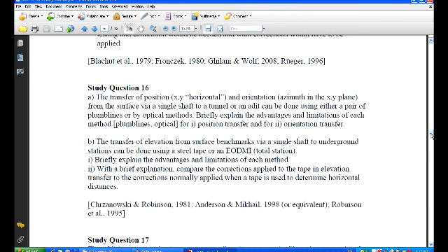However, there's also the problem that with an optical plummet you either have to be above or below where you're wanting to have the horizontal positioning done, which means if there's a sump at the bottom of the shaft, there would have to be a fairly sophisticated platform, and you can imagine how sophisticated it would have to be in order for the instrument not to be vibrating. And similarly, there would have to be a similar type of effort up above.